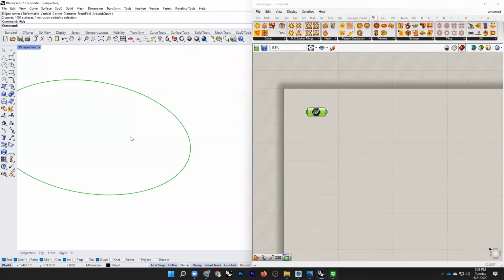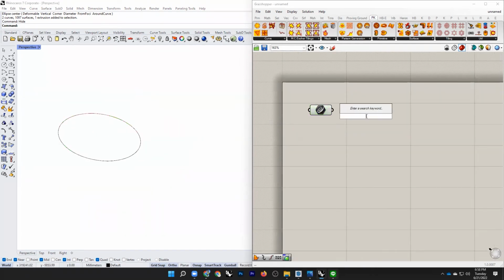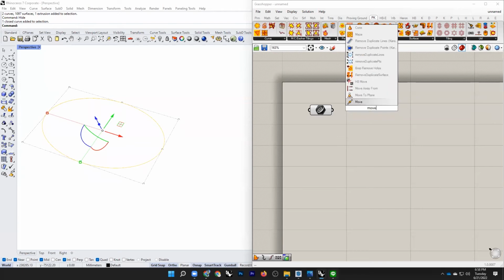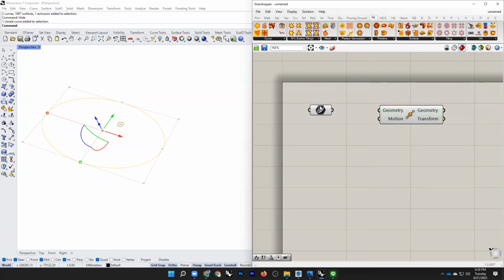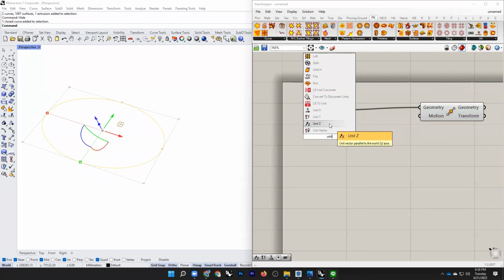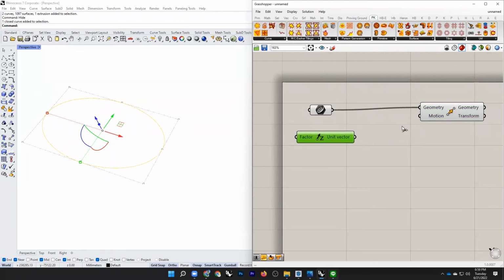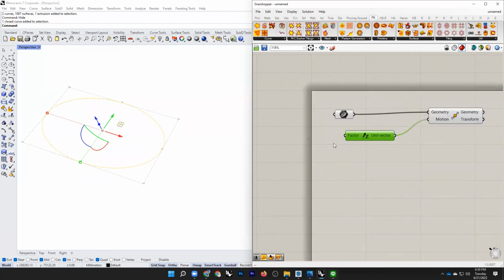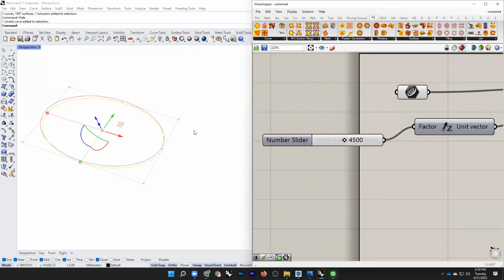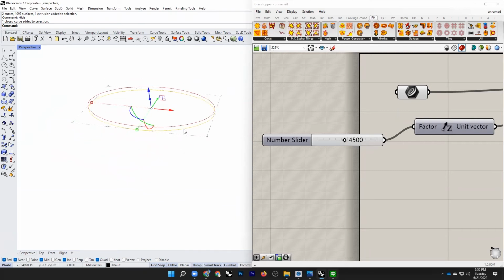Okay. So say we have a few floors for this shape of building. I will just copy this floor. So I will make a move element. I will move this element in the vertical direction, so it's unit Z. Okay. And I will move one floor, say 4,500 millimeters. So I will give here 4,500, which is one floor. So you can see.